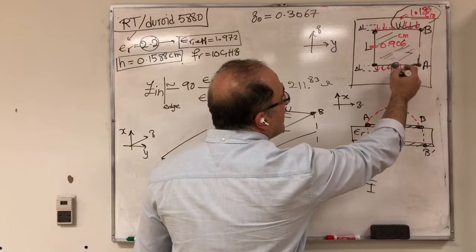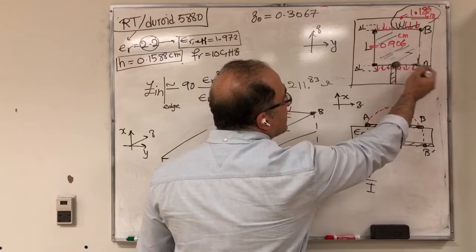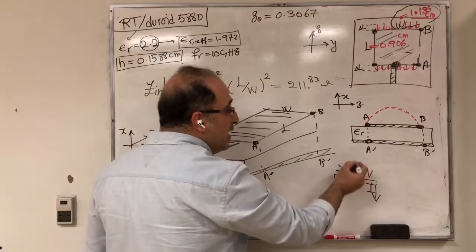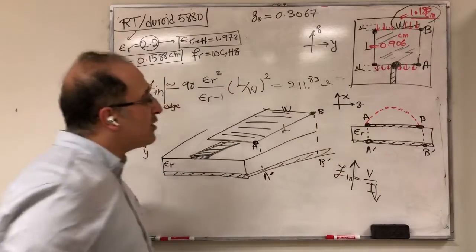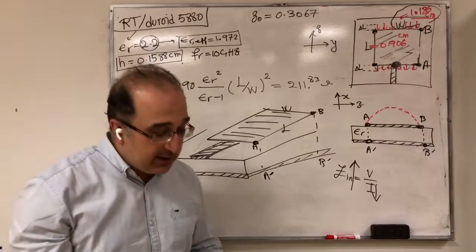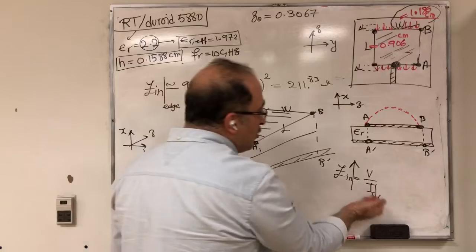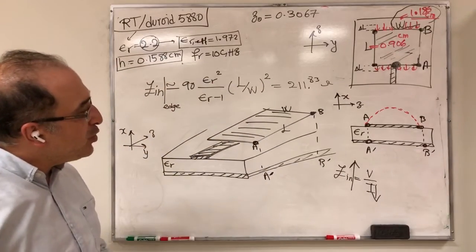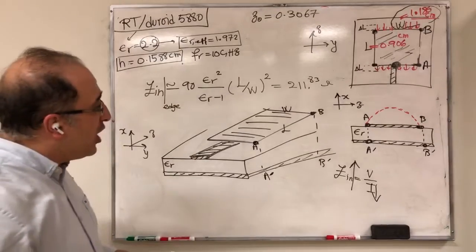So when you are calculating your input impedance at this point, you are essentially dividing by a very small I, so your input impedance becomes very large. And in this particular case, large is 211 for us. But if you go by approximation, you say I goes to zero, Z in goes to infinity. So this is the problem that we have, and we somehow need to solve this problem.